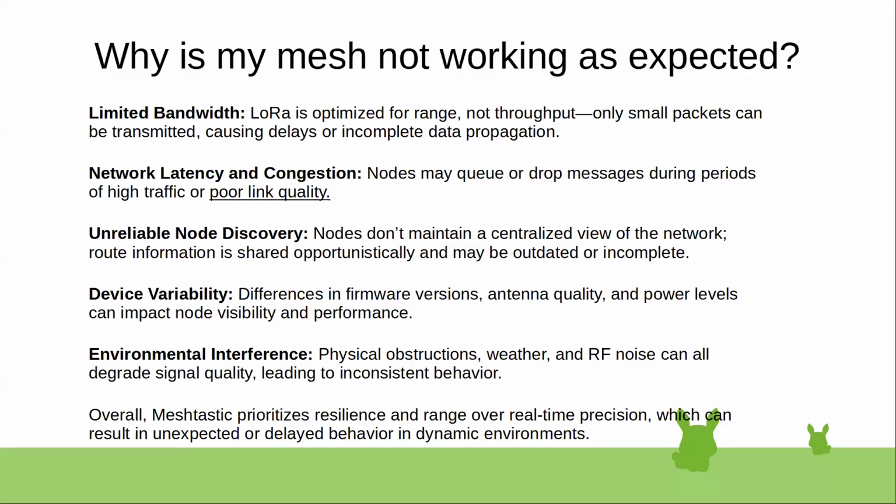I don't think we've put anything near a big commercial transmitter yet, but I feel like we might start getting some interference somewhere like that. You can get bandpass filters for the 915 band. I'm putting one on my home node eventually because it's right next to my 2-meter antenna, and it can't hurt. Also, if you live down the road from an FM station, it probably can't hurt. They're like $40, and I've seen a lot of people say that helps quite a bit, especially in busy RF areas. But out here, it's not particularly busy for RF.